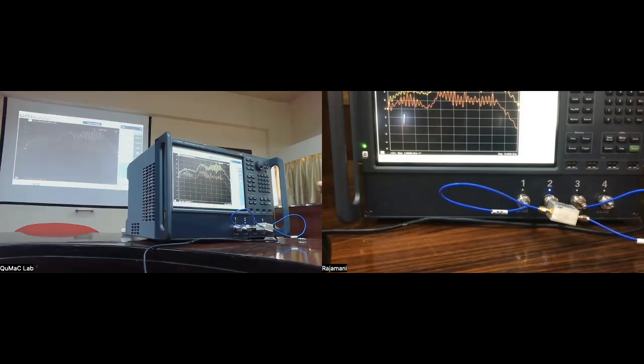The 4-port version of this device, which has the sum and the delta port, will do the exact opposite. If you send in signal through the delta port, the two signals will come out 180 degrees out of phase with each other. Okay. So let me not say too much to confuse things, but the delta port for this device is actually internal to it. You don't have access to it. It's the design of the Wilkinson divider.